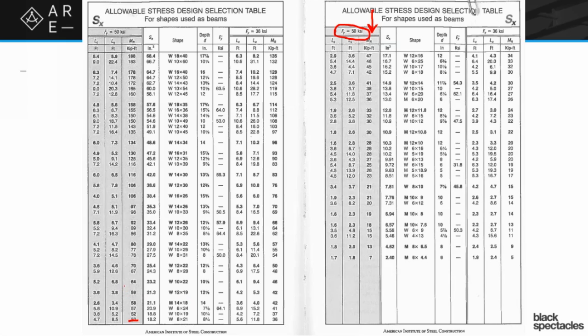So here goes the key thing of understanding about the wide flanges and the idea of efficiency, especially as regards the exam. When you're talking about structures, you talk about efficiency, you're essentially talking about dollars. Well, how do you understand dollars in steel? It's about weight. And since the wide flange, the first number is the nominal height, the second number is the weight per linear foot.